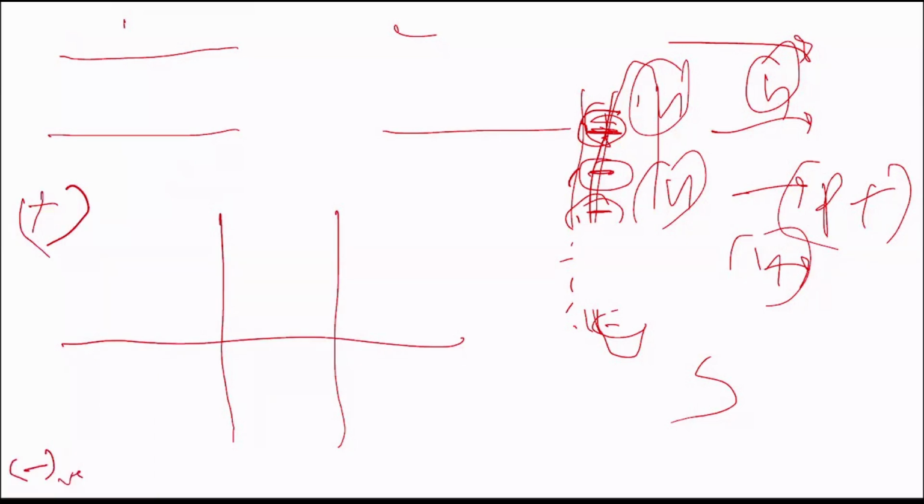If it is above the y-axis, it says that we have positive charge, and here it is negative charge. This is the metal region, this is the oxide region, this is the semiconductor region. So now if we apply a positive voltage across the metal, then we have a depletion region. If we increase the positive voltage a little bit, the depletion region will increase a little bit. If we increase it a little bit more, the depletion region will increase a little bit more.